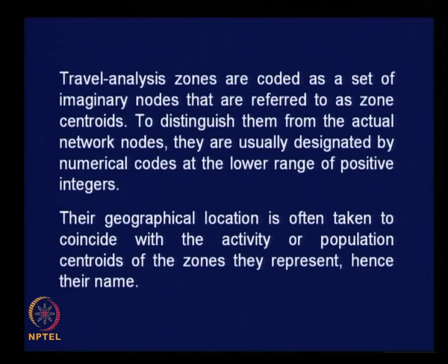When we say zone centroid, it is not the geometric center of traffic zones, it is the center of activity if it is a non-residential zone, or the center of the spread of population if it is a residential zone.